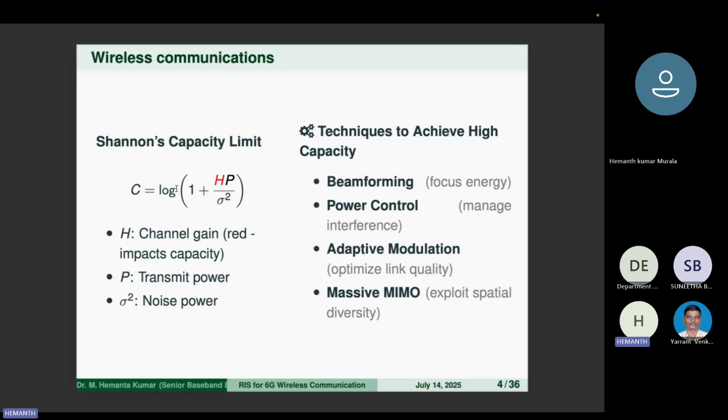This is the zero forcing equation. This is a mathematical equation, and it all depends upon the H. H Hermitian means H transpose only. If it is a matrix, you can use the Hermitian. This is mathematical logic: H Hermitian H inverse H Hermitian. So I can multiply it with my transmitted signal. I know the X signal, I am the transmitter. You are the receiver. So before the signal reaches you, I will multiply the transmitted signal X with this factor. Clear?